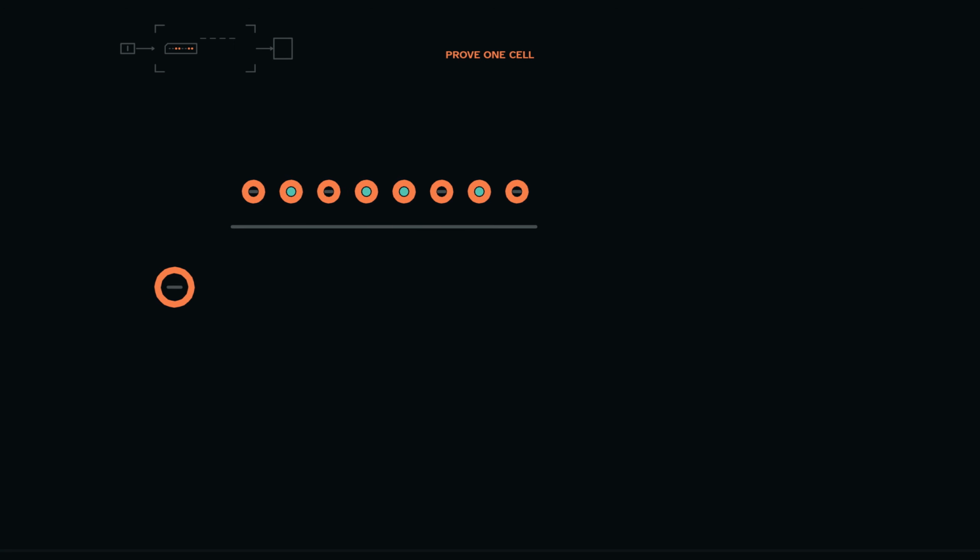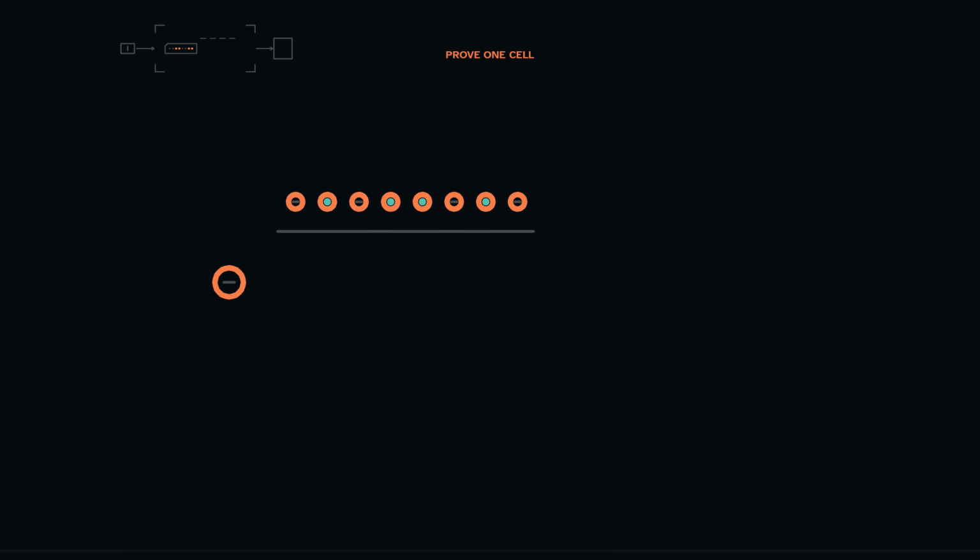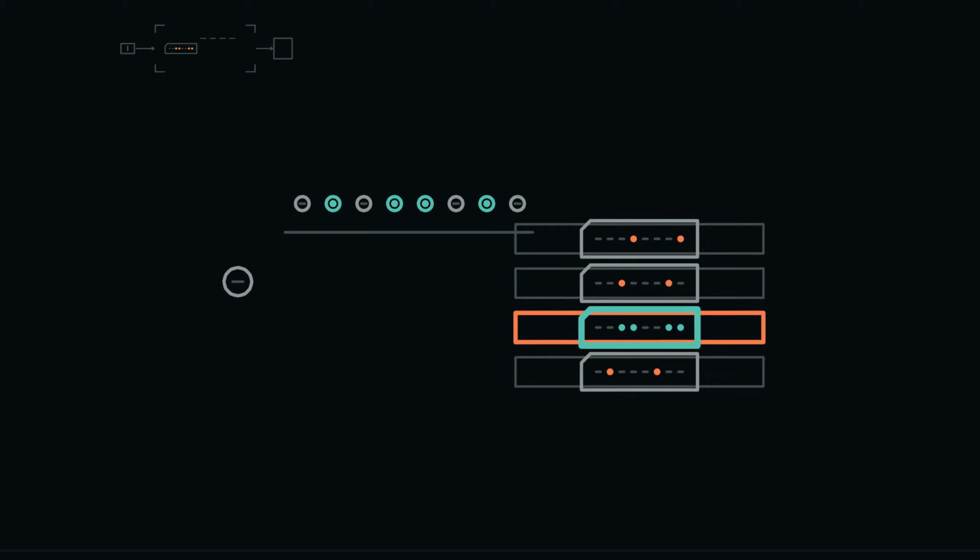Replicate that cell across 8-bit positions. All 8 cells share the row's write permission and edge, while position 0 receives data bit 0, position 1 receives data bit 1, and so on. This creates one byte row. The row is not 8 independent mystery boxes. It is 8 instances of one tested rule with a declared position mapping. Predict the result when the input is hexadecimal 5A and the row is selected at the edge. The 8 cells capture 0, 1, 0, 1, 1, 0, 1, 0 in their fixed order, so the row stores hexadecimal 5A.